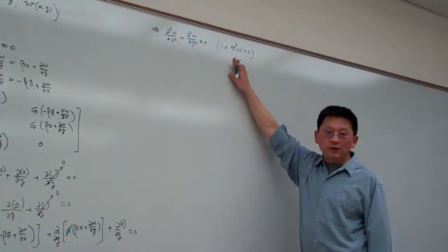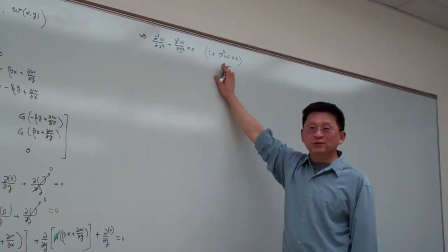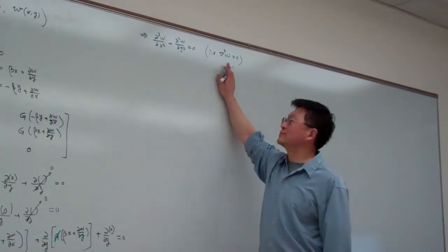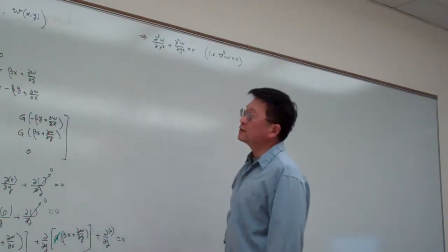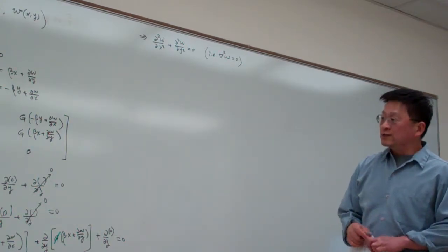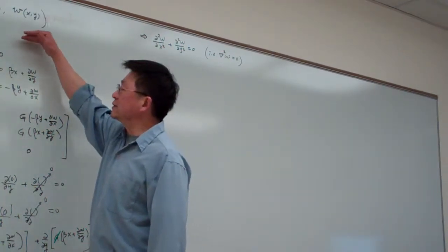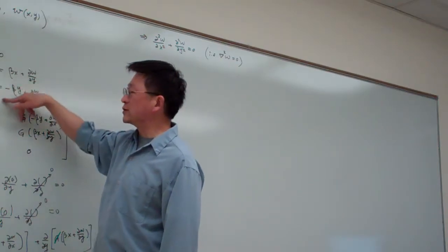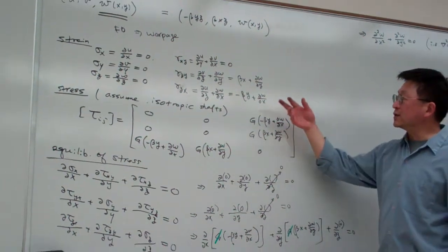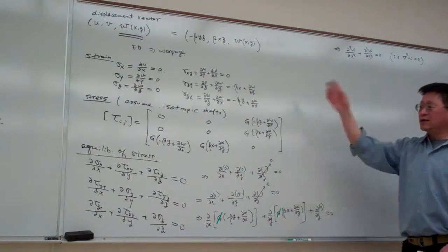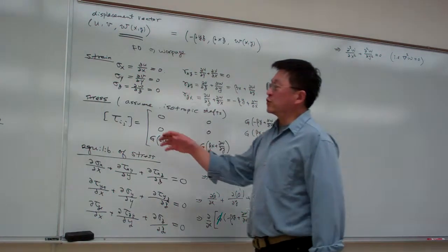Again, I believe some of your class projects are working on the last equation, its solution form, hopefully. So to this point, we pretty much have everything we need, combining the strain-displacement relations, Hooke's law, and the equilibrium of the stress, with compatibility embedded trivially in here. So basically here is everything we have, and that is the general formulation for torsion of the prismatic shaft.